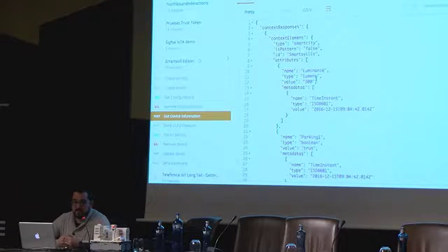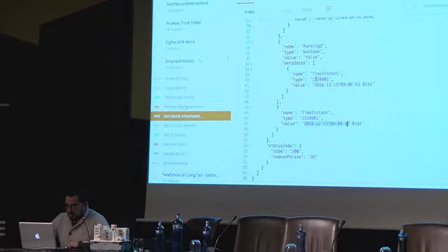So a device can be sleeping and waking up from time to time, can be storing measures with different timestamps, and then send all of those measures with different timestamps, and that will appear in the IoT agent with the timestamps where they were taken instead of the timestamp where the measure arrived to the platform. And so that is for data send.